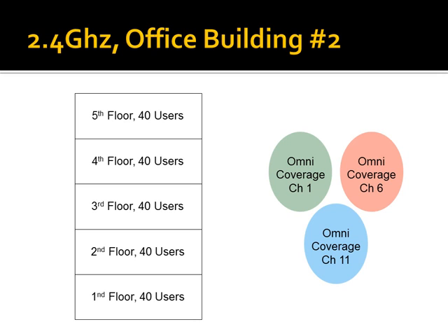And the reason is, how does this omni antenna actually radiate? If we take this antenna and turn it up like this so that we're looking at the side of the antenna, how does it actually radiate? What's the pattern? Yeah, it's an annulus. In other words, this is a donut with the antenna sticking up through the middle of it. So we do have more radiation in the azimuth direction, the direction I can point as I turn around, if I ignore up and down.